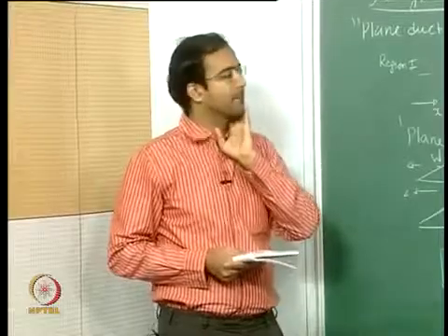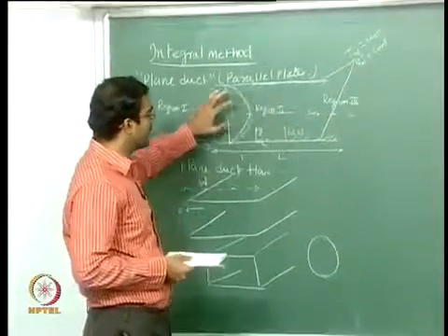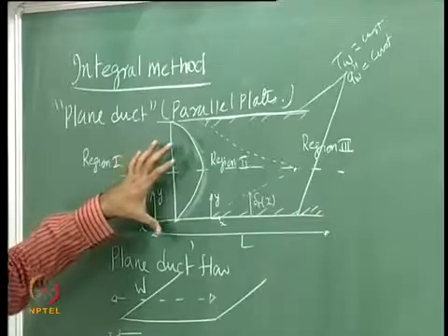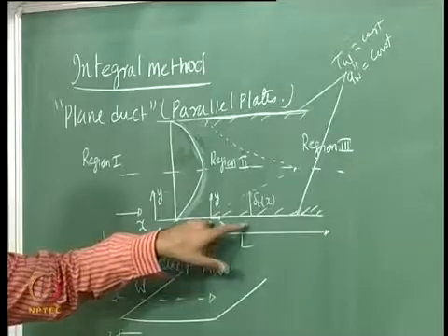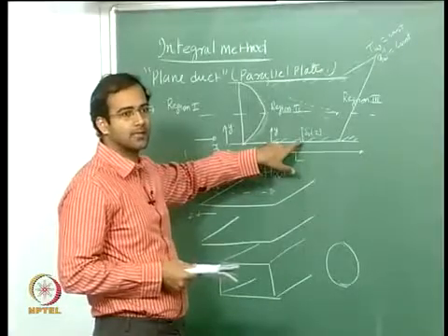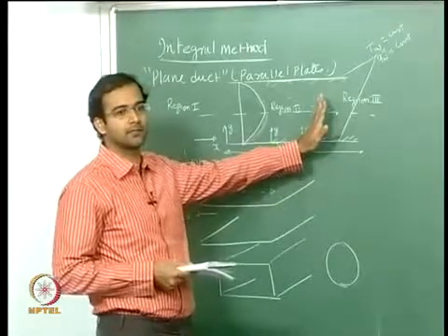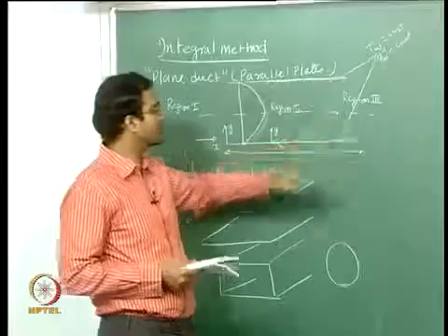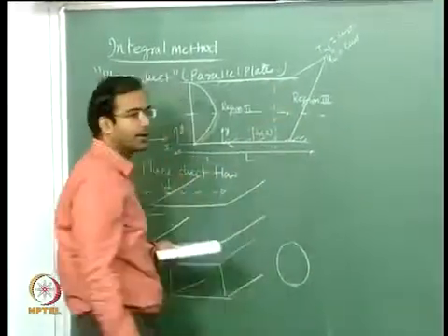Yeah. So if you look at region 2, if you have the fully developed velocity profile, then you can focus on region 2 where you have a boundary layer like structure. Okay, so that is only up to a certain distance downstream. If you go further down, you can see somewhere here it loses the boundary layer like structure.